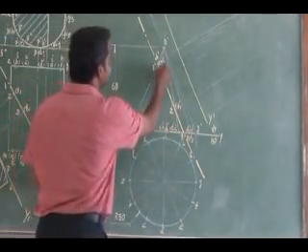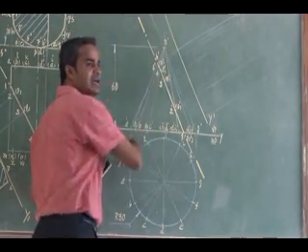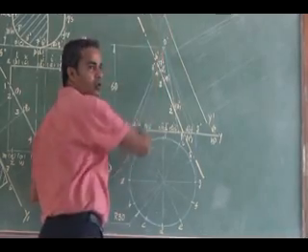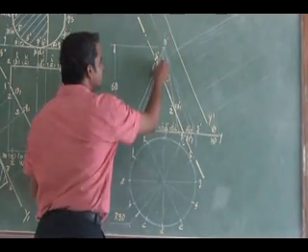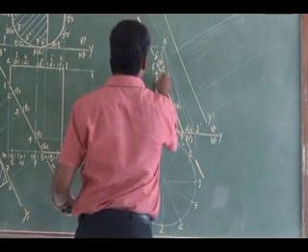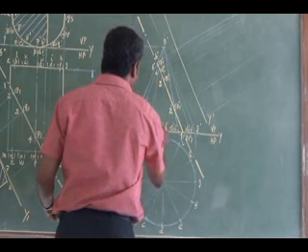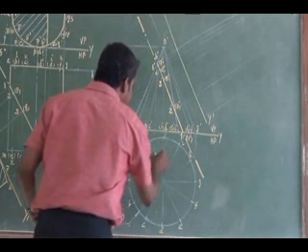So you see, look at this, the extreme cutting point is 6. 6 is on which generator? AO. Right, 6 is on AO. Just I am projecting AO vertically, cutting point 6, vertically to the top view. Listen carefully, listen.